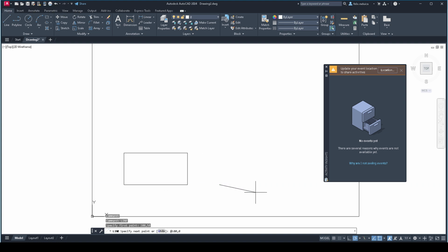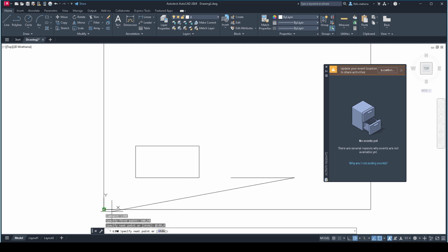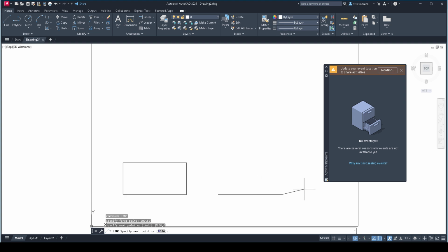This means that consider now, so I'm telling the software, consider now that the last given point is your reference and create a 100 millimeter line from that point. So consider that point to be the temporary origin. When I tap enter, it will create that point for me. So if I write the @ symbol in front, then it will no longer consider this to be the origin, but it will temporarily consider the last given point.